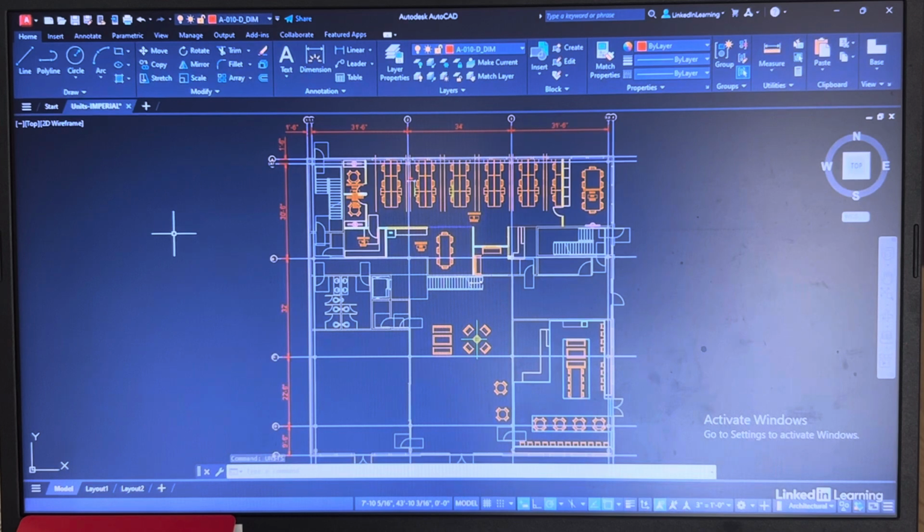So as you can see, it's very easy to check what units a drawing is using, but when you set up a new drawing, there's no way for AutoCAD to kind of go, oh, you're in millimeters, or oh, you're in inches. You've got to set all of that up by setting your units display first and getting everything up and running in the drawing. So just be aware of that. AutoCAD won't do that part of it for you.